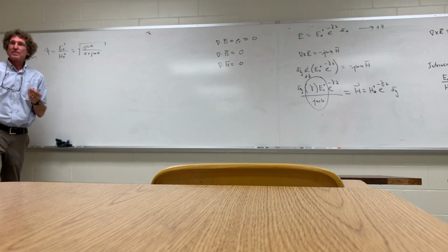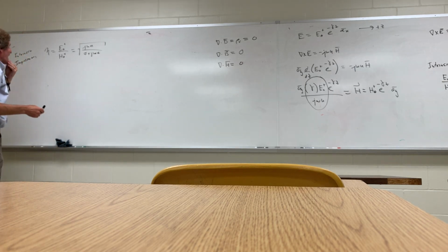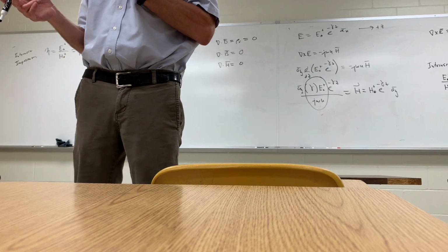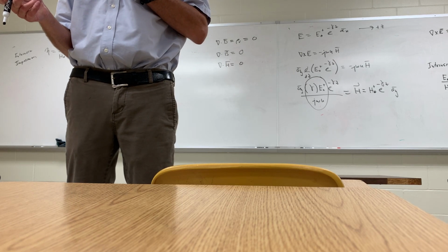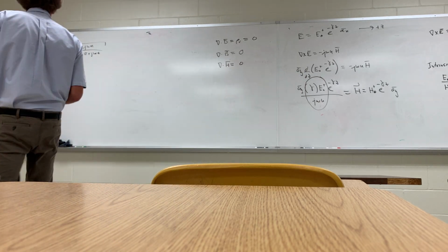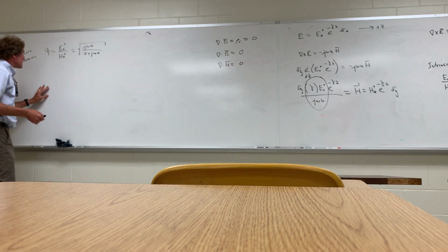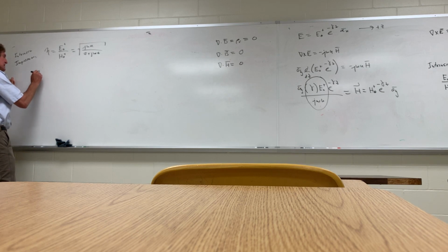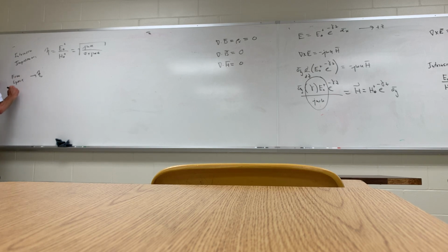What does that really mean? Well, you remember how when you had transmission line theory, you learned something about the characteristic impedance of the transmission line, right? That was the ratio of V naught to I naught. Do y'all remember that class? It didn't have anything to do with the DC resistance or anything like that. It had to do with propagation. And this is similar. The intrinsic impedance of the region, if we talk about what it is for free space, eta naught is going to be the free space intrinsic impedance.